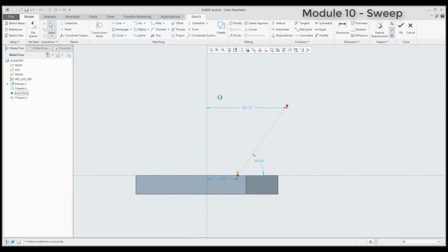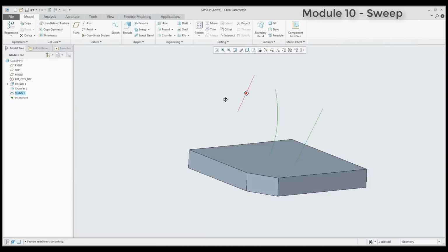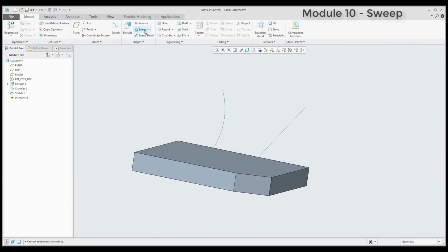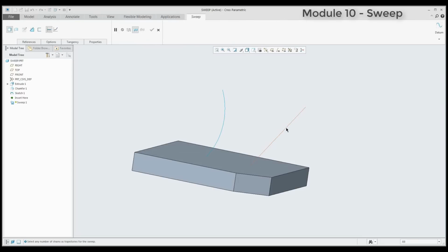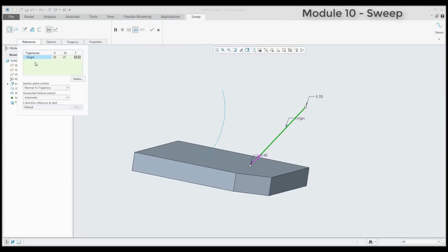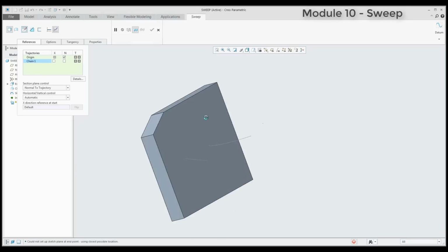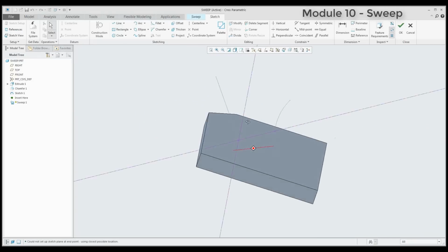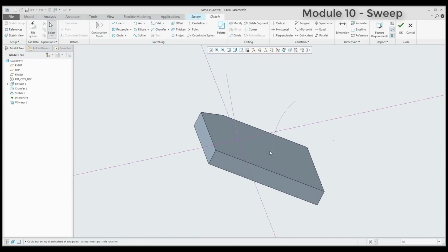In the existing sketch, for the first example, I'd like to add only one curve. For example, same as this, and it will be some arc. And right now, you can see that for the sweep feature, I can select the first curve. It will be selected as the origin. And if I use the Control button, the system automatically jumps to variable section sweep. And right now the system allows me to use existing curves in the sketch here.